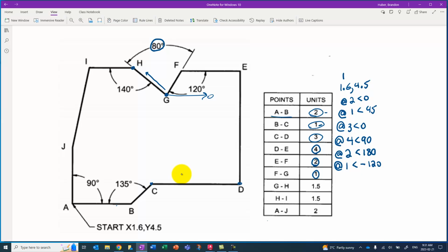And here's how I would approach it. We already know that we have 120 here. If I extend the line like this, we now have this supplementary angle situation again, where I can figure out this angle because it needs to add with 120 to make 180. So that makes this 60 degrees. Now if I take 60 and add it to 80, that gives us our included angle.